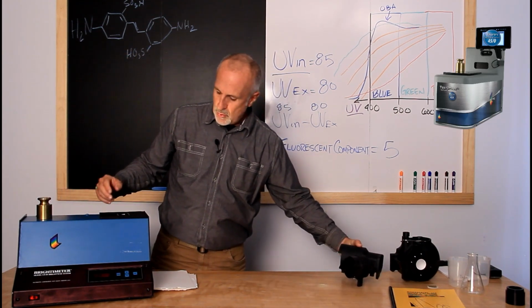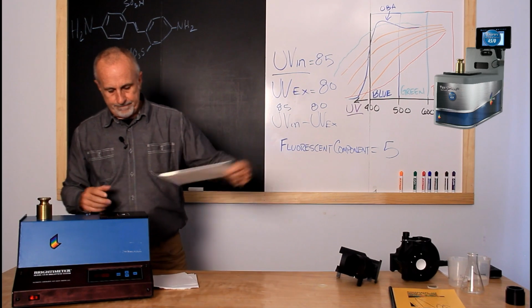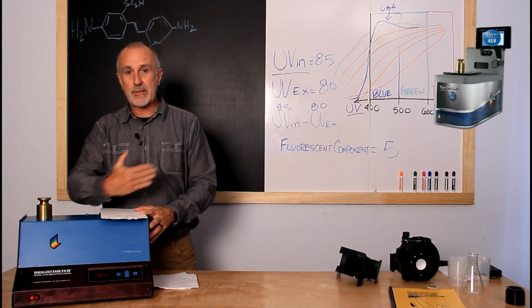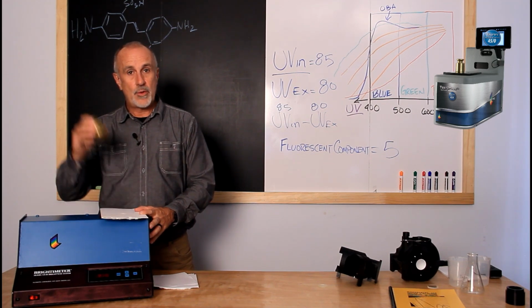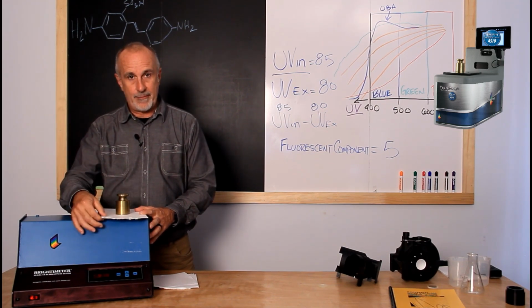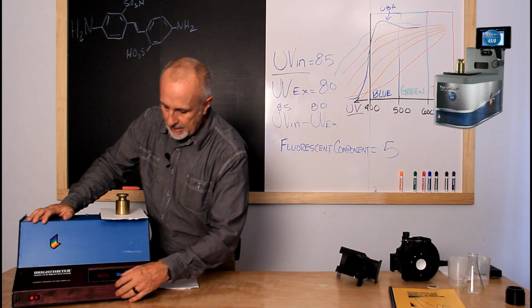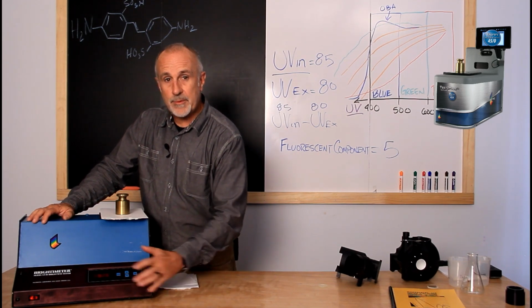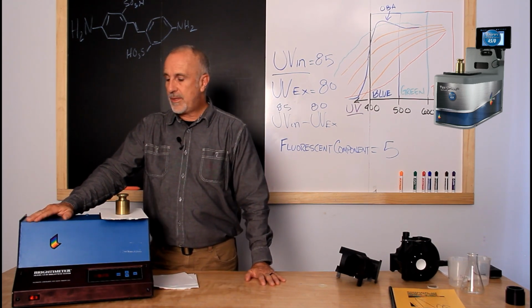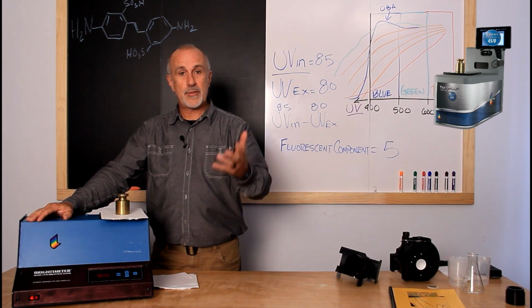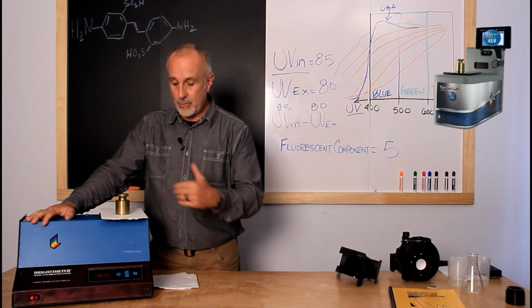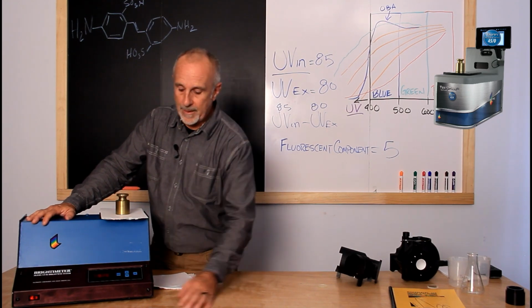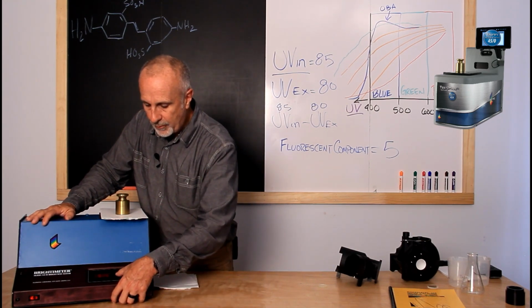We will take a sample, and I will load that sample, and the machine direction of this sample is running this way. So I load that on there. Always use the 1 kilogram weight and an infinite pad when you make measurements. And this instrument is equipped to measure fluorescence, and with the next generation of this and the Test Plus, it also has that fluorescence app that you can get, which allows you to do the exact same thing that this is doing. Okay, so I push and hold the fluorescence button.